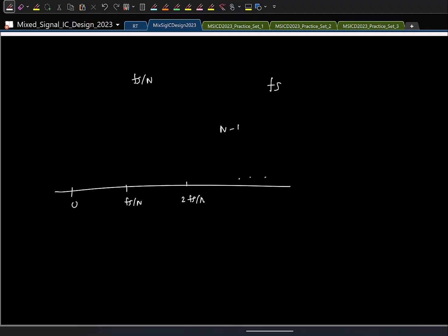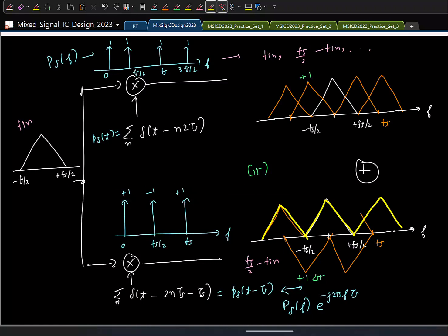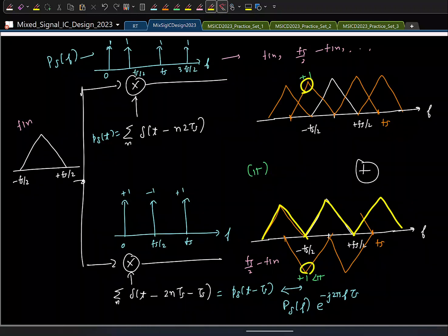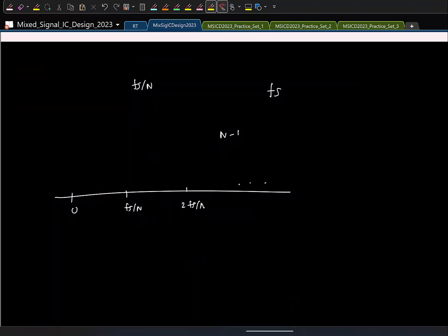And here you see that in the 2-channel case, the phase shift of these images between adjacent channels is pi. Similarly, for an n-channel case, the phase shift of the images between adjacent channels, what will that be? Pi by n. No, for 2 channels it was pi. Oh, 2 pi by n. It will be 2 pi by n. Okay. So basically now you will have n images, magnitudes will be the same, relative phase shifts will be 2 pi by n.